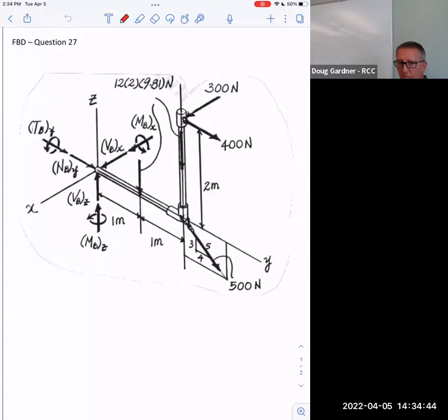But notice that's the proper free body diagram that we just drew, except we only had 2 dimensions because there was really nothing happening in X, but notice he's got stuff happening in X, Y, and Z here. And so here's the pipe. It's split right there. That's where the break is, and that's where he drew the axes in. So he's got X over here, Z up here, and Y going back this direction.